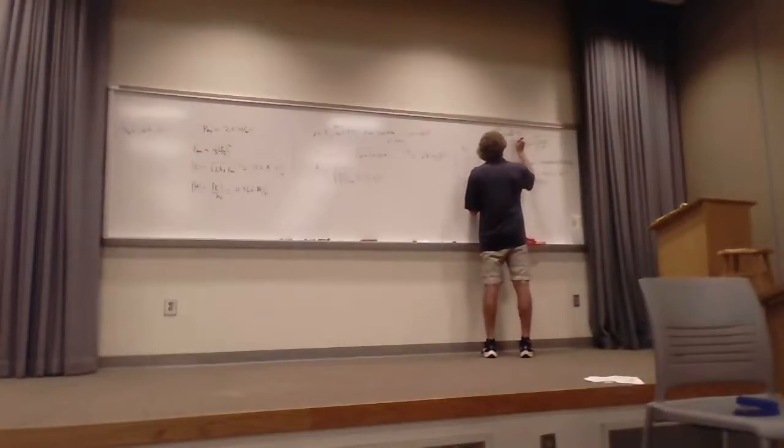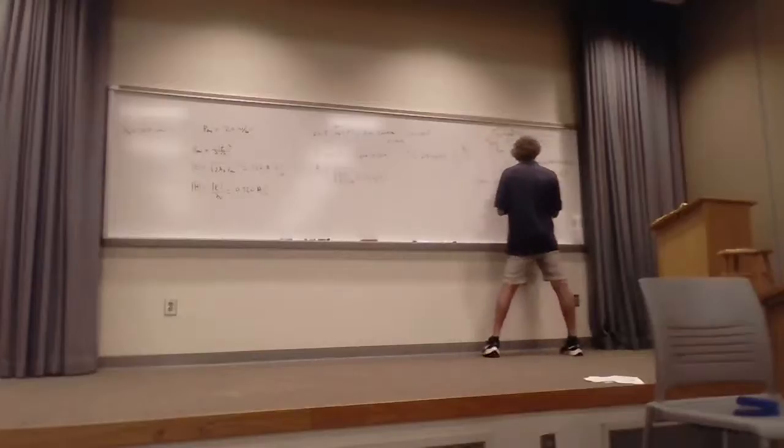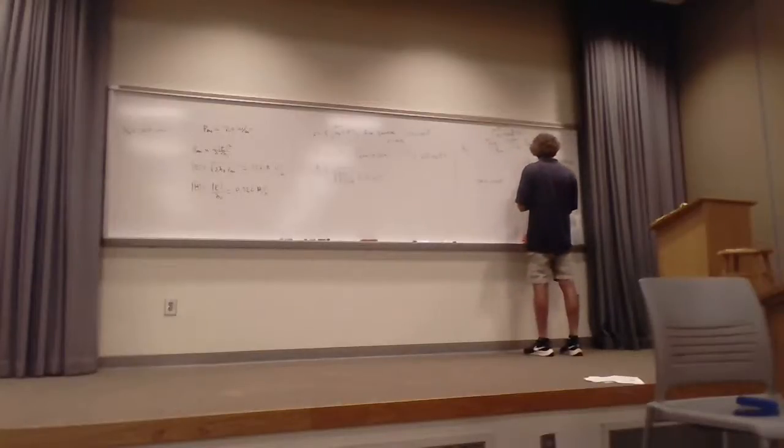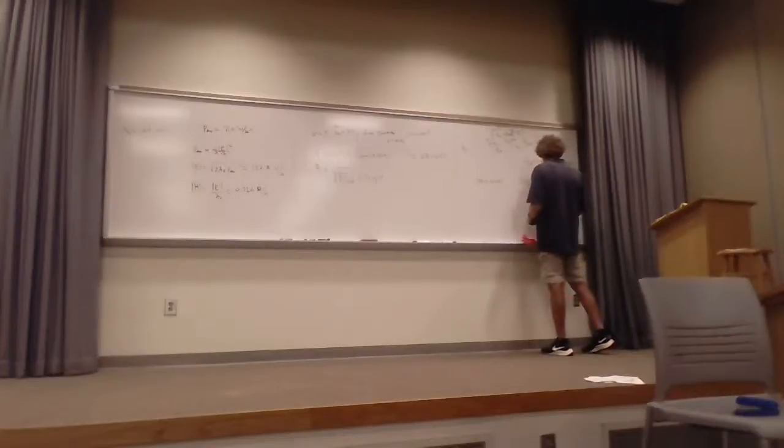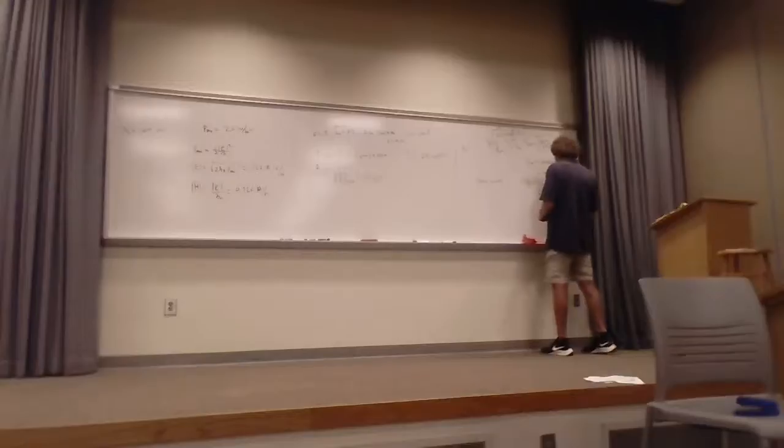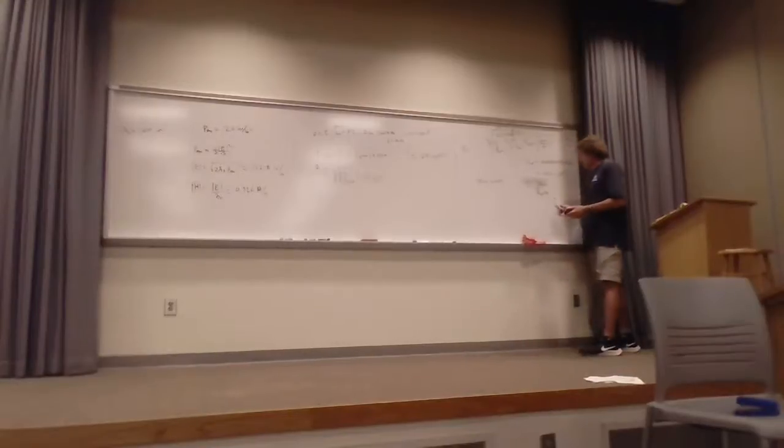And then we need the transmission coefficient in 2 is equal to 2 eta shield, it's always twice the impedance you're going into, over eta shield plus eta naught. This is a small value, but here you can almost ignore eta shield down there. It's really 2 eta shield over eta naught. You all follow me? Because eta shield is so much less than this. You all follow me now?